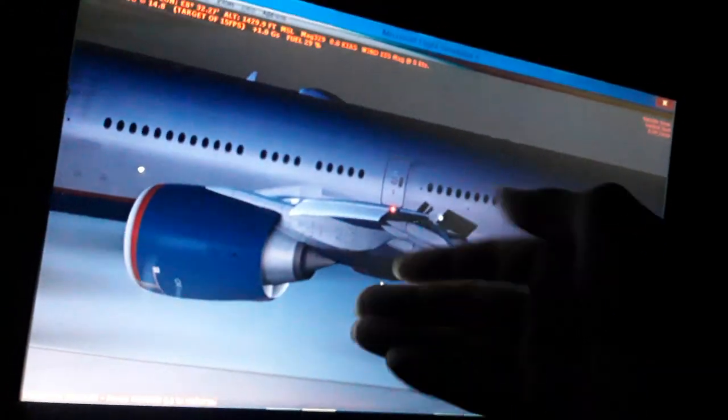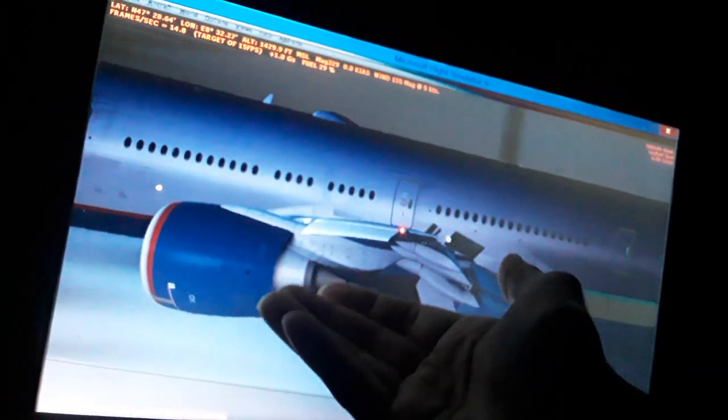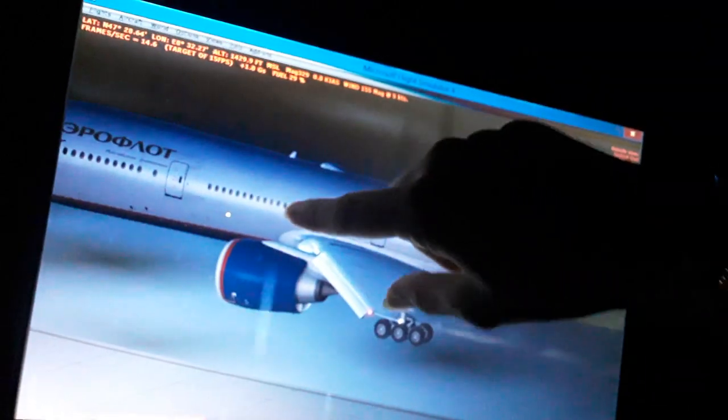the air mass per second times the acceleration of gravity, is the lever arm and moment arm. Also, you can see the bottom surface of the wings is more flat, so as we accelerate for takeoff, the airflow of the air mass, using Bernoulli's theory of fluids, is moving slower, so we have higher air pressure below the wings, which pushes the aircraft up into the air. Also at the top surface of the wings, the airflow of the air mass is moving much faster, so we have lower air pressure, which sucks the aircraft wings up into the air. So these are some very quick aerodynamic principles. Very quick.